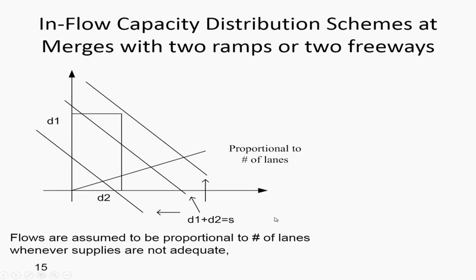So before I move into more details or the more practical consideration, I would like to use this simple illustration to show how literally the DTALite has to keep track of the capacity allocation. So in this x-axis, this is a freeway on-ramp. On this y-axis, this is the freeway mainstream section. Suppose the on-ramp has one lane. This mainstream section has 3 lanes.